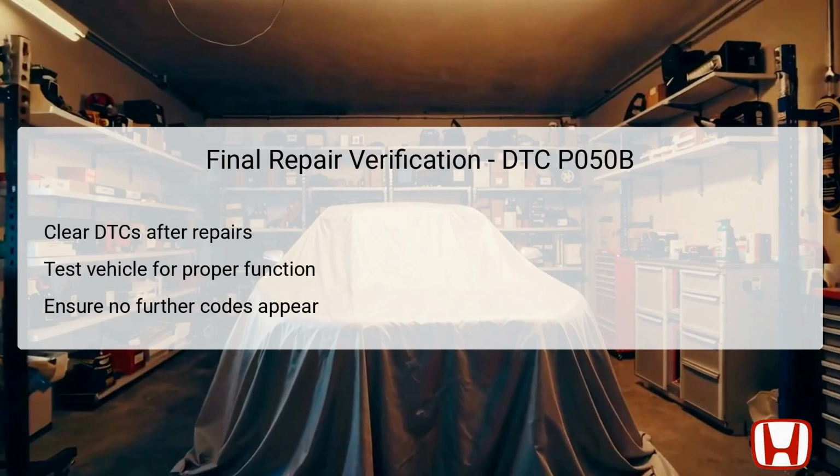Once all necessary repairs based on the previous diagnosis steps have been completed, it's time for final verification. Begin by clearing any DTCs present in the system using the HDS. Following this, conduct a test drive of the vehicle to evaluate performance under normal driving conditions.